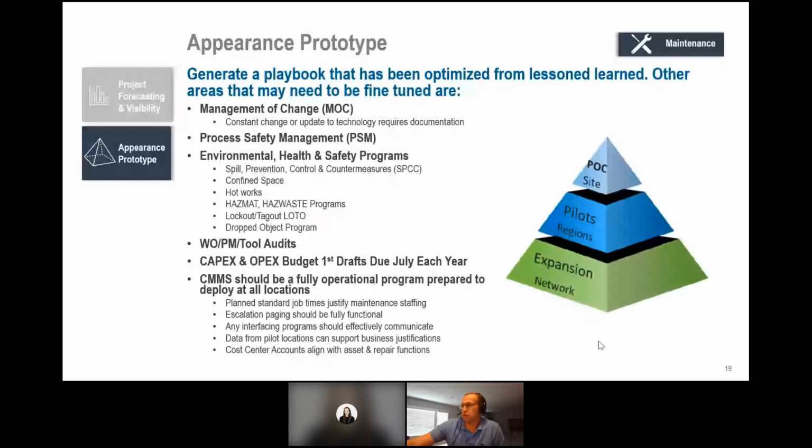It pretty much changed a lot of stuff within our safety manuals, because we had to go through revisions and updates as our process changed. So that'd be something to consider. If you have an ammonia refrigeration site, or if you practice good process safety management, always go back in. So if your 14 elements of PSM, I put change management first, because that's always something that needs to initiate that process. Go through your change management or management of change checklists.